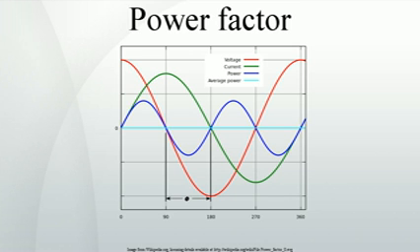A typical switched-mode power supply first makes a DC bus, using a bridge rectifier or similar circuit. The output voltage is then derived from this DC bus. The problem with this is that the rectifier is a nonlinear device, so the input current is highly nonlinear. That means that the input current is energy at harmonics of the frequency of the voltage. This presents a particular problem for the power companies, because they cannot compensate for the harmonic current by adding simple capacitors or inductors, as they could for the reactive power drawn by a linear load.